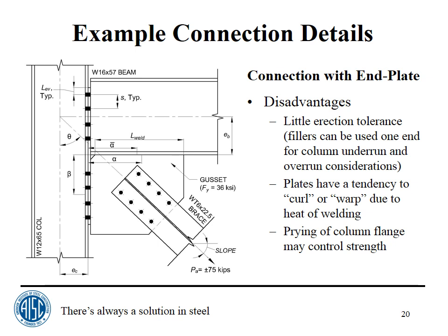Okay. And then, in addition, here's another question about the end plate connection. Is it fair to say another disadvantage is having to drill through the column flange? Absolutely. That was one of the things I think I said for the end plate. I mean, it double clips end plates. You've got to drill column flanges. There's no question about it.